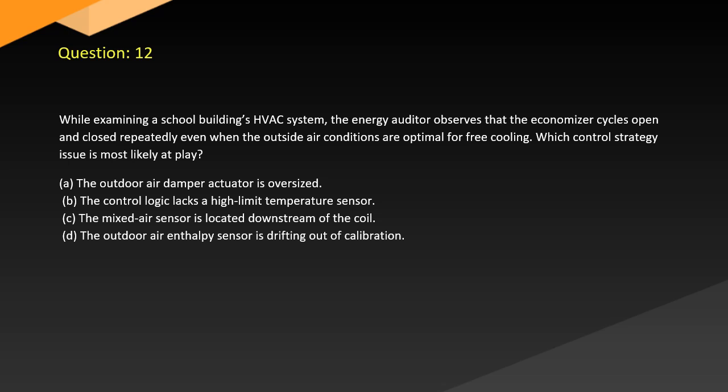A. The outdoor air damper actuator is oversized. B. The control logic lacks high limit temperature sensor. C. The mixed air sensor is located downstream of the coil. D. The outdoor air enthalpy sensor is drifting out of calibration.